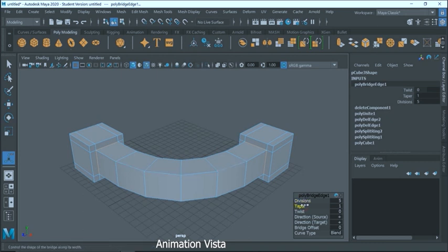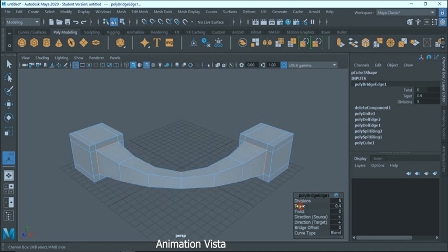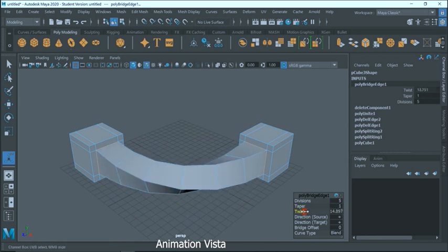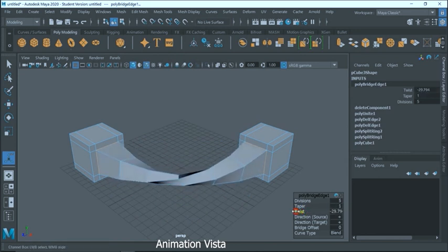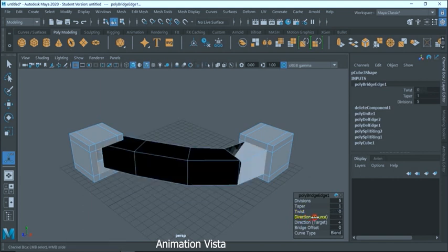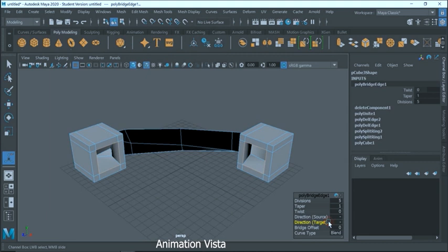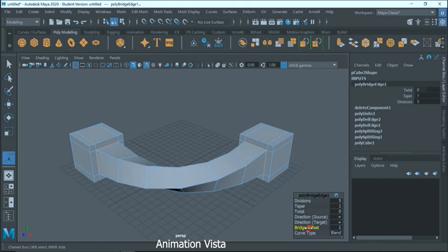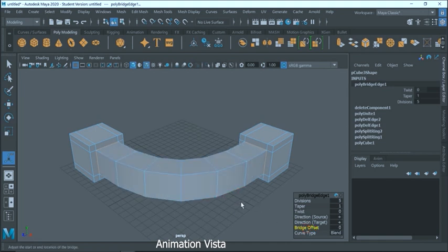Using taper, you can change the shape of the bridge, whether it will be straight or bulged in or bulged out. Using twist, you can rotate the bridge and hence it is called twisting. Both of these direction attributes help in changing the direction of the bridge from positive to negative side of the selected edges and vice versa. You can use the bridge offset the same way as twist, except that it uses a different approach than that of twist.